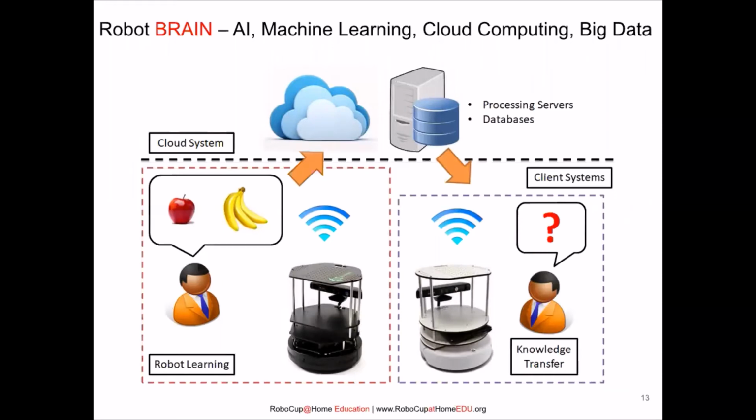Because we are building a very simple robot, we don't have a very sophisticated or high-end specification. We just use a normal laptop on the robot, so we focus its resources on the local operation, for example navigation, getting the data from the sensors, and processing the data. But we want to push all the computing power that is not required on board to the cloud.